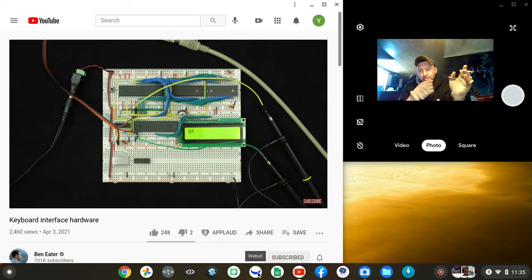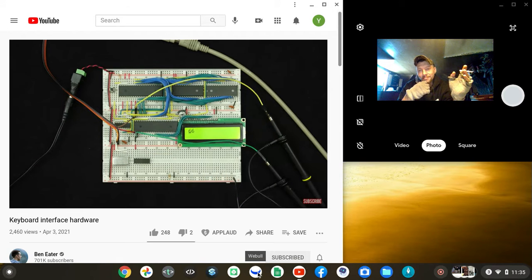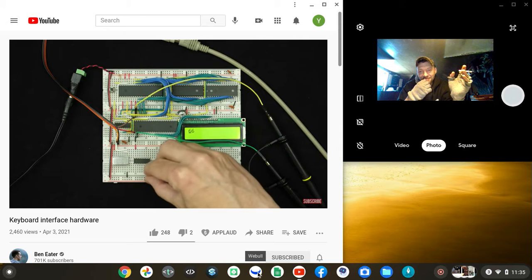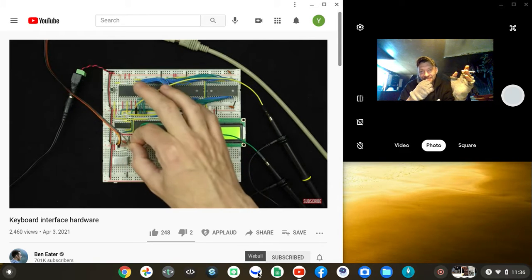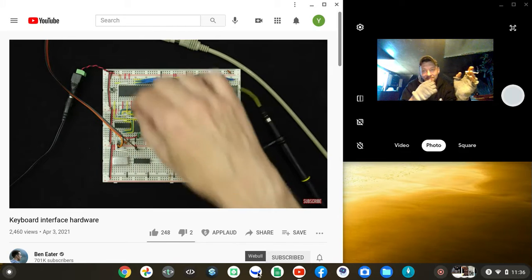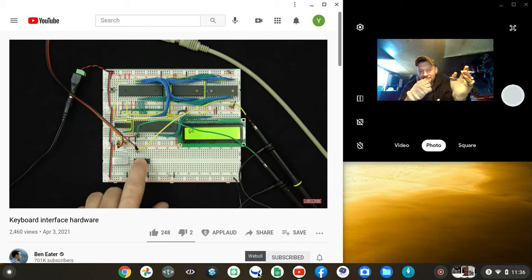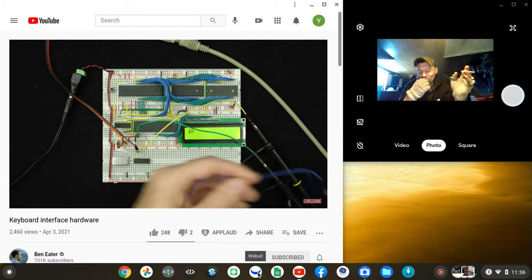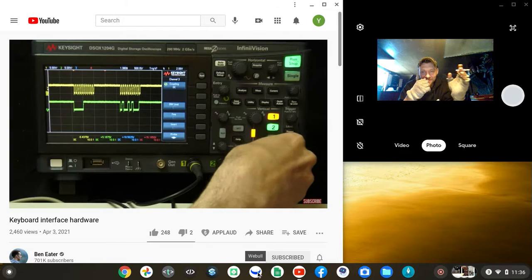For the capacitor to discharge through the resistor. So what I'm doing here is just hooking the clock signal up to an inverter. This chip is a 74HC04, which has 6 inverters on it. I'm hooking the clock up to that so that we are inverting the clock signal, so that we have a high going pulse for each clock, which we'll need anyway for the shift register. So the output of the inverter is here, and we can hook up another oscilloscope probe to take a look at that. So I'll get that connected.